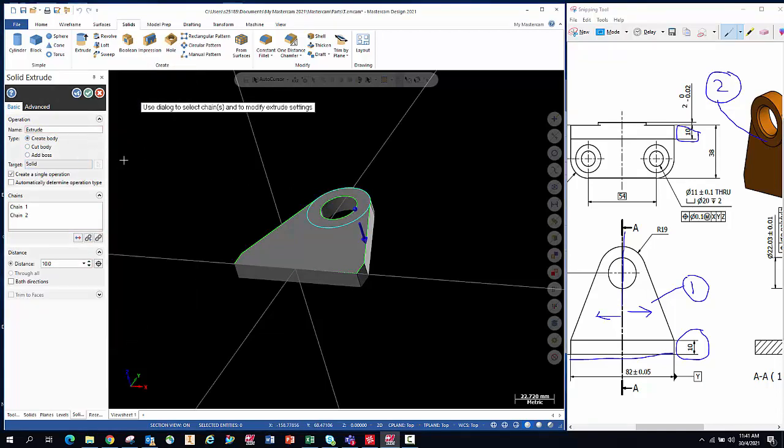It will give you the preview as well as the direction. Right now, the direction is going to extrude downwards. But of course, I like the boss to go up, so I can reverse. Now this becomes a boss. But the boss is not of the height of 10 mm. It is only of the value of the mean value of this amount, which is 1.99. So I will update this to 1.99.